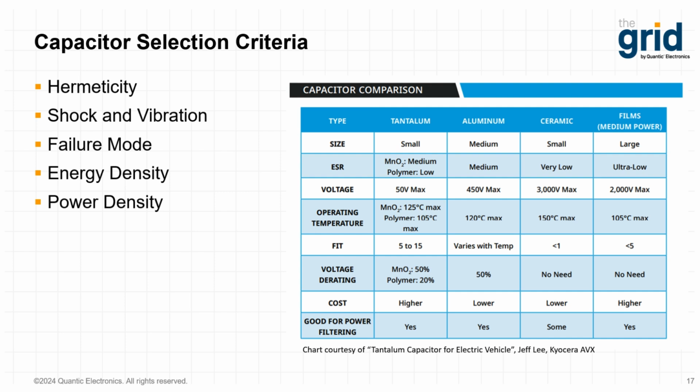Now, going back to MIL Standard 202, there's a variety of shock and vibration conditions that electronic components must be tested to. So it's always important when choosing a capacitor for an application which has a lot of shock and vibration to get in contact with the capacitor supplier, to find out which MIL standard it adheres to. The supplier will be able to let you know what MIL standards these capacitors are tested to and designed for, and can go from there.